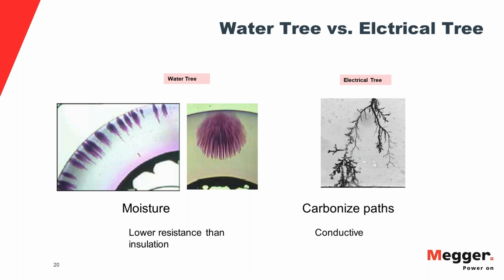I'm going to just talk briefly. I'll let Robert answer most of this. But it'd be like monitoring leakage current on a DC high pot. You can watch your leakage current going up during the time of the test, and if you start seeing a trend, that gives you the indication that there's a soon-to-be fault, maybe something that isn't actually going to fail the cable under your hour, but gives you the opportunity to extend your test time out and try to cause that fault to fail under your test condition.